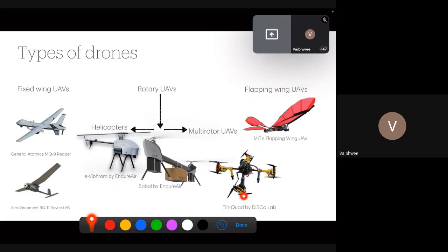The multi-rotor, which you see with some yellow parts attached to it, is one of the vehicles that we are working on in our lab. Here, unlike the helicopters which have just one single main rotor, it has multiple rotors which are responsible for generating the lift. This is a 4-arm arrangement where on each of the arms there are 2 rotors which are put in a coaxial arrangement.